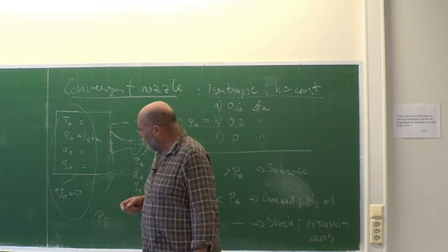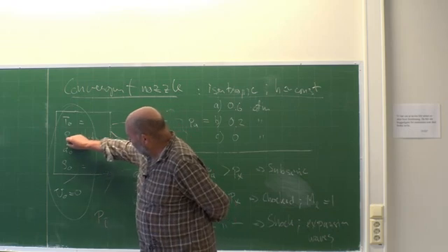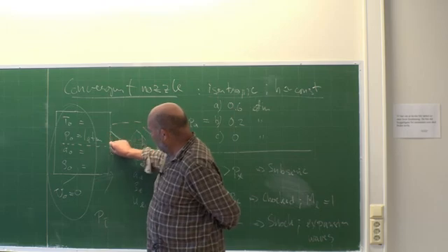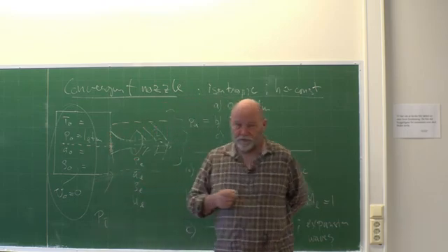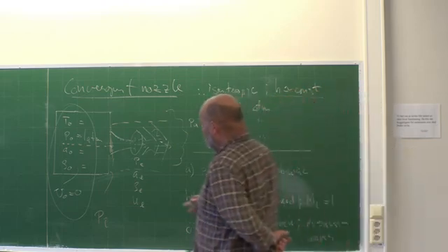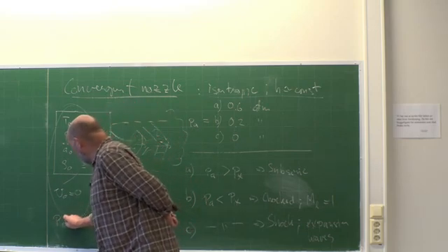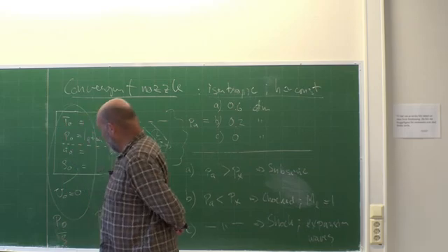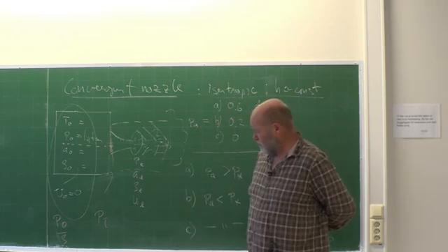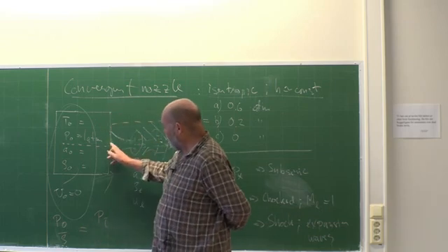And then if you can sort of imagine trivial Bernoulli from somewhere inside this reservoir along a streamline hitting our inlet into this divergent nozzle. What do you get? Well, on this side you will have the pressure by density, and we don't have a velocity, we don't have any gravity here, no problem there, equals whatever you have here.